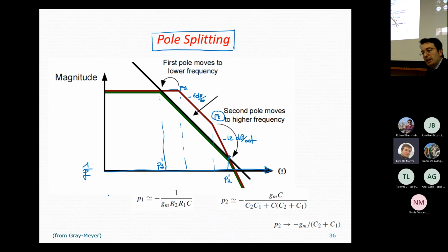Okay, so a quite relevant current will flow from VDD. Then we have also in the current balancing at this node the effect of this transistor number 7, which is driven by a constant gate voltage. Okay, so I7 is basically constant, while I6 and I5 are influenced by the biasing condition of this device.